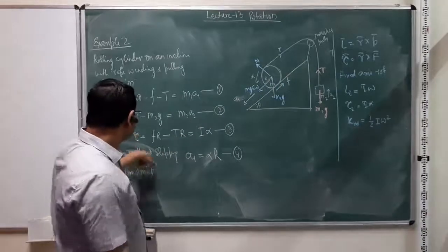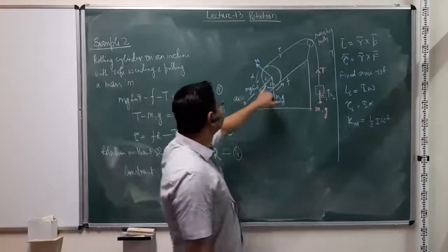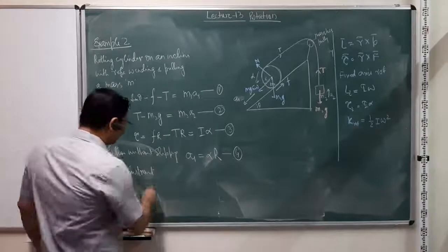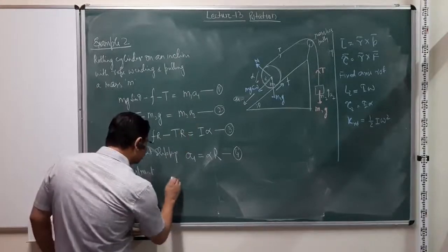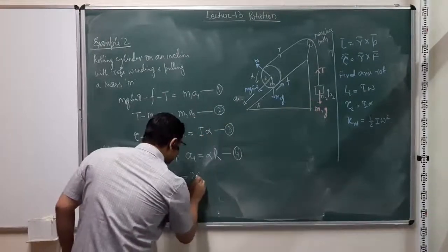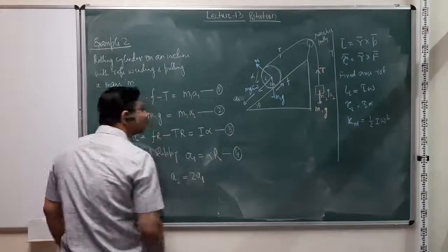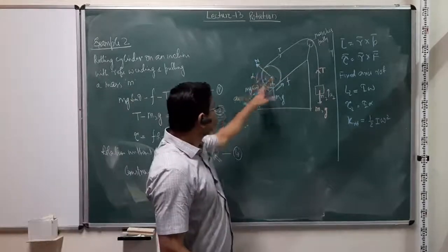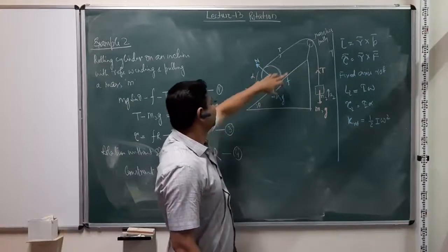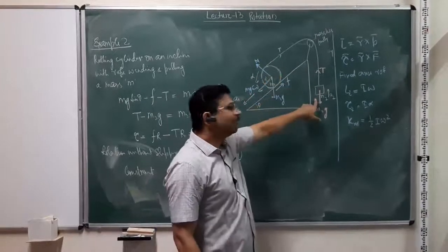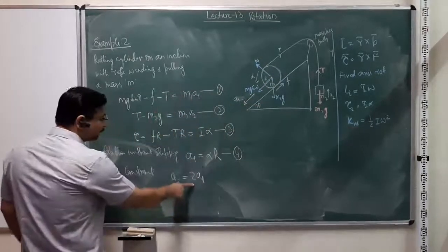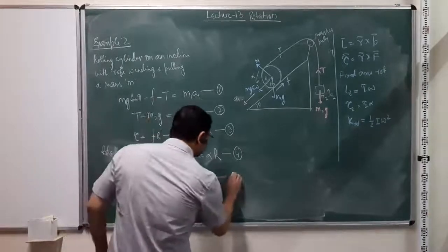However, because of this rotation without slipping and the drum and this mass being coupled to that string, we'll have a constraint condition which basically will then say that A2, acceleration of this is equal to twice of A1, right? So if this one winds around, let's say 1 turn, then the drum also moves some distance, the rope winds around on this, so this one makes an additional motion compared to the drum, right? So A2 is going to be equal to twice of A1, and then this is my equation number 5.